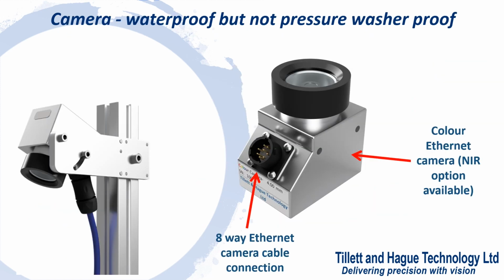The camera is mounted within an aluminium casing with O-ring seals specifically designed for the agricultural environment. However, they will not withstand pressure washing, and it's prudent to store them undercover, especially during the winter. There are no user serviceable parts inside, and it's important that the seals are not broken, as moisture ingress will lead to misting inside the camera glass cover and will degrade the electronic parts inside.